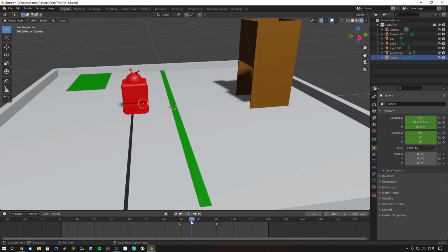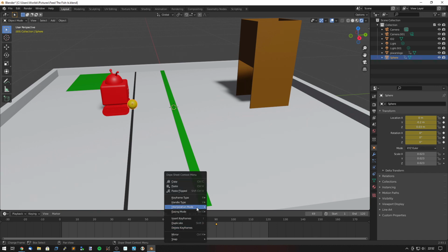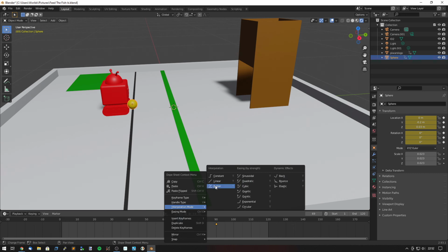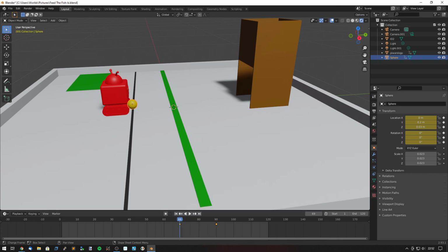But as I move this forward, you can see, well, it's because the keyframes by default are working off sort of interpolating in a different way. So we can go to right click and interpolation mode. There's like a Bezier curve, linear or constant. I think by default it's Bezier curve. So it kind of accelerates, gets to a speed and then decelerates as it interpolates, rather than just interpolating between those two over that frame.